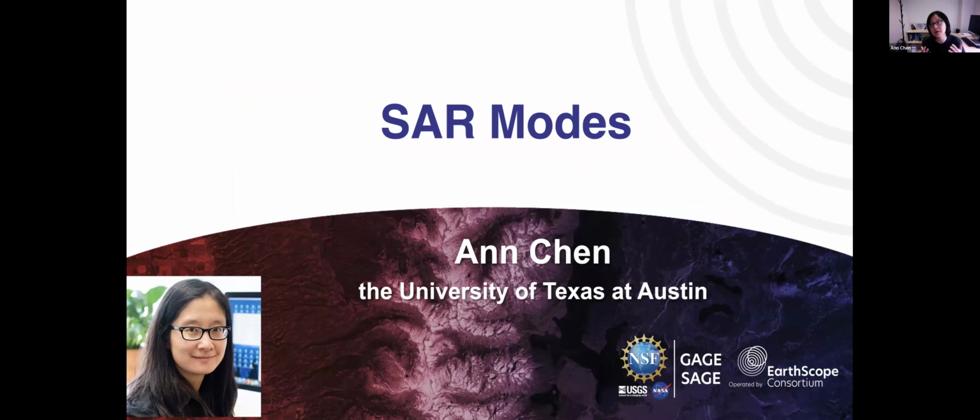No matter what imaging mode you use, you should get a pretty good quality interferogram for surface deformation analysis. But the trade-off is really about spatial resolution and signal-to-noise ratio. And more importantly, we hope to get a wider swath so that we can reduce the satellite repeat cycle. That turned out to be a very critical trade we would like an imaging SAR mission to have.